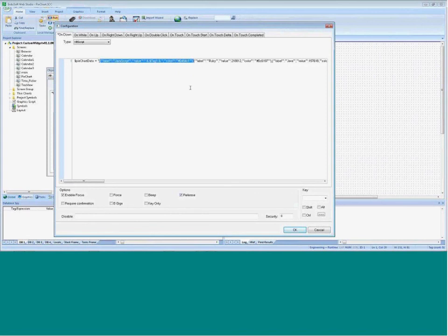Now this is not an InduSoft format. This is a standard called JSON, J-S-O-N. In this particular case, I've separated out three things: the label, the variable, and the color. I'm passing it JavaScript, a tag that I have on the slider, and then a color. And then for all the remaining pie slices, I've just hard-coded those in here so we can see how this works.